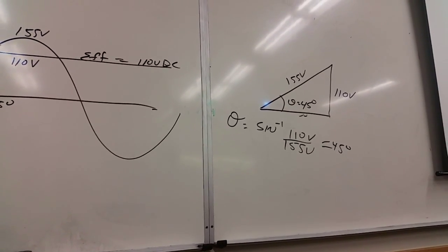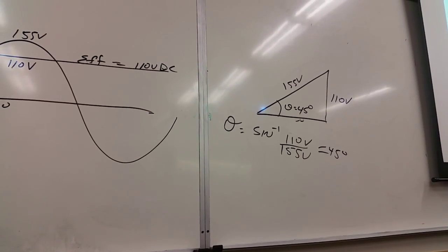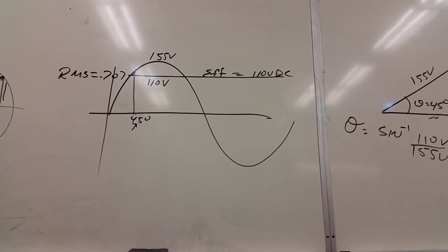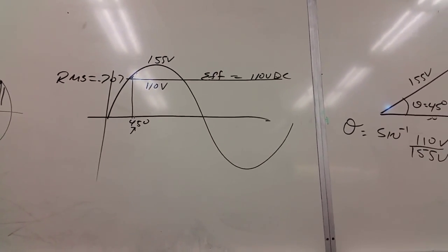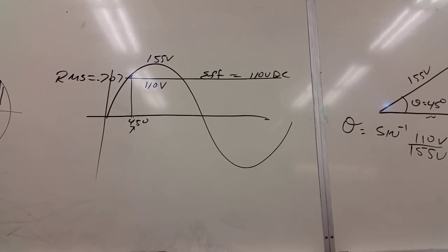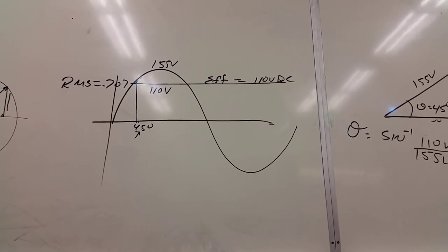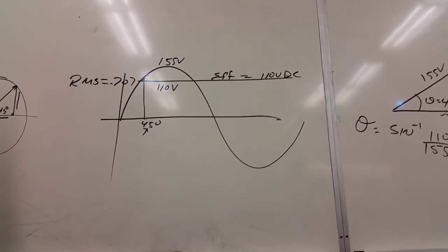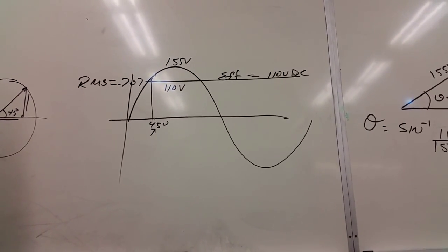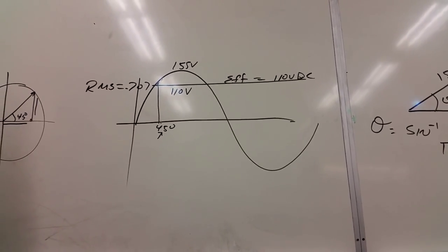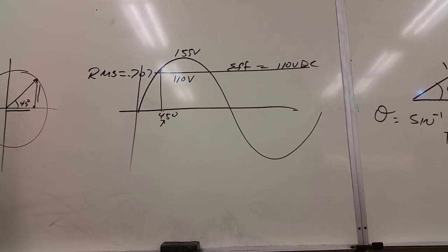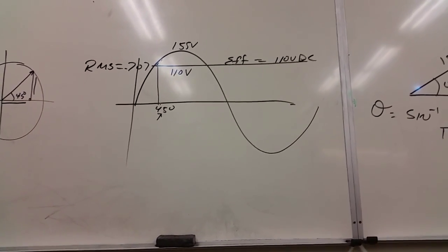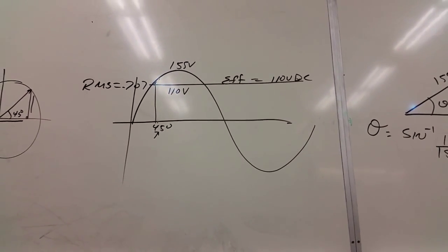No, every time you read your meter, it reads RMS. So this is what your meter reads, RMS. Every time you get that meter out and read something, it's reading an RMS value. So you're saying to reach that value, you're going to have to put in more volts? Correct, than really what's being displayed. Would you be able to measure your peak? An oscilloscope? Yeah, you'd have to have an oscilloscope.